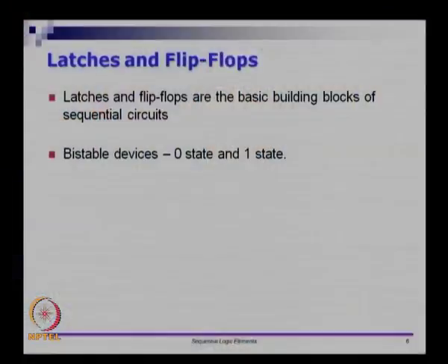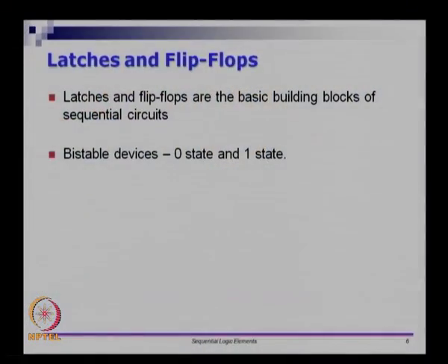So to do this, we have different kinds of basic logic elements. Latches and flip flops are the basic building blocks of sequential circuits. The first thing is that these devices, both the latches and flip flops, are what are called bistable devices. A bistable device is one in which, if you are at logical level 0, it will remain at 0 and it is a stable state, and if you are at logical level 1, it will stay at 1 and that is also a stable state, unless there is a condition which moves it to the other state.